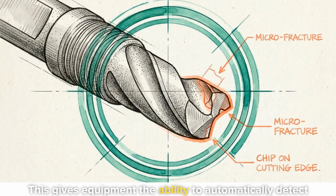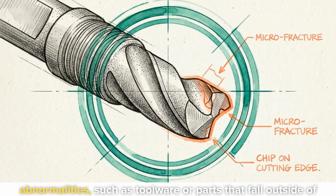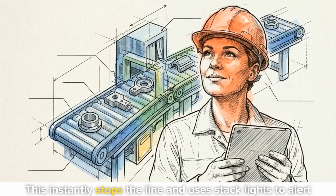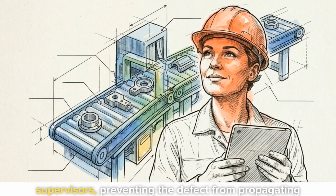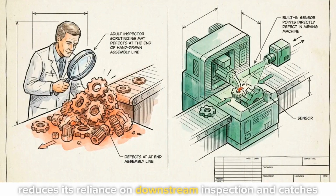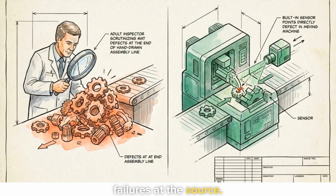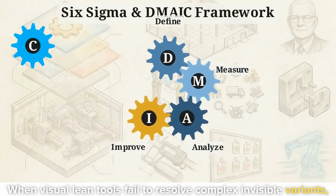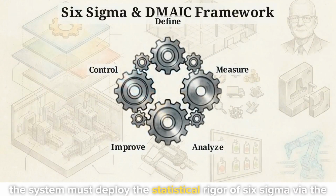This gives equipment the ability to automatically detect abnormalities, such as tool wear or parts that fall outside of tolerance. When a defect is detected, Jidoka triggers an andon system. This instantly stops the line and uses stack lights to alert supervisors, preventing the defect from propagating downstream. By anchoring quality within the process architecture, the system reduces its reliance on downstream inspection and catches failures at the source.